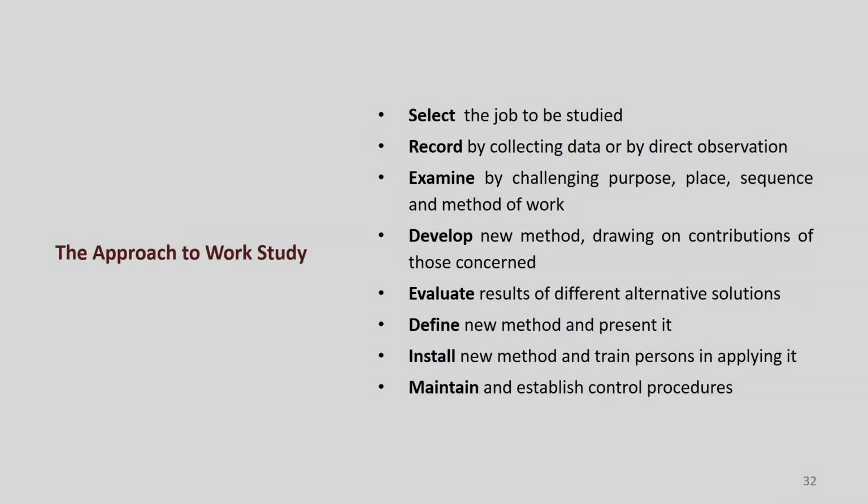So, what are the approaches? First, we select the particular job we are going to study, and record it by collecting data, by indirect observation or by direct observation. Then examine it by challenging the purpose, place, sequence and method of work. Then develop the new method. You can create a drawing with the contribution of those concerned, evaluate the result, define the new method and compare.